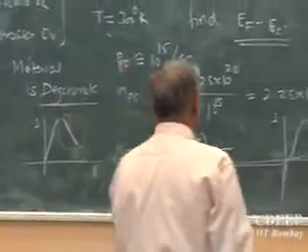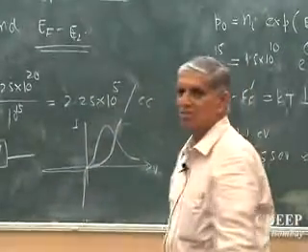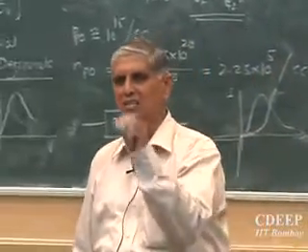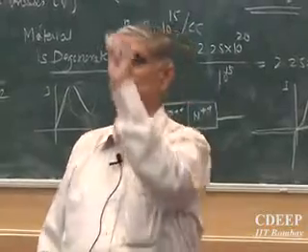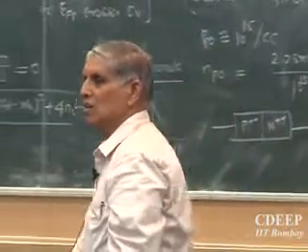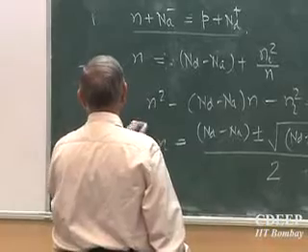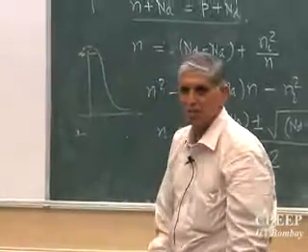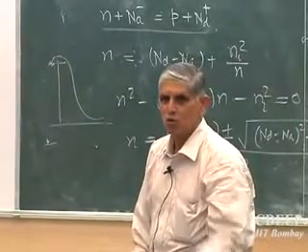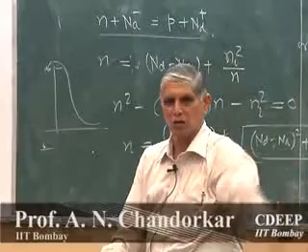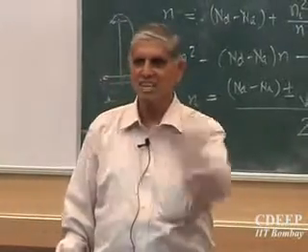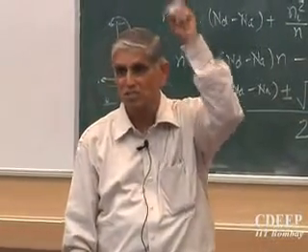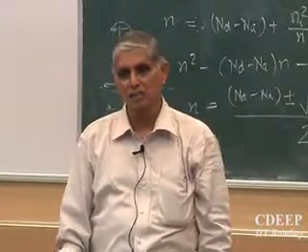Why am I showing you this? Because in a normal diode, the rise in current is initially very small and then starts rising exponentially. This is essentially because electrons have to cross a certain amount of potential barrier. In the case of tunneling, the barrier is never crossed. What do we do in the normal case? Let's say this is my barrier energy. If I am an electron, I have to go like this. This is called thermal emission. So much thermal energy is provided that electrons cross that barrier and jump. If electrons can find a state on the other side, they can come directly without climbing this much energy. Is that clear? This is the phenomenon which is interesting, different from thermal emission.